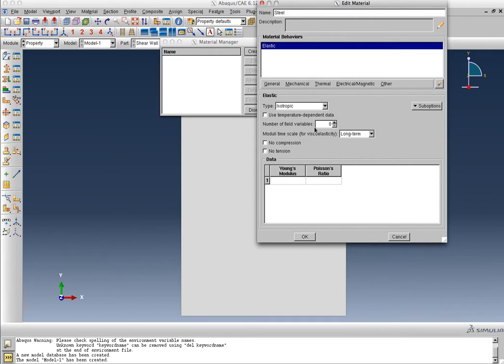And it asks me what type of elastic model it is. In that also there are options. There's isotropic. You can make an FRP made up of lamina. You can have orthotropic and isotropic elasticity. Well, we're in the simplest problem, so it's isotropic elasticity. I'm going to specify the E to be 29,000 ksi and the Poisson's ratio to be 0.3.